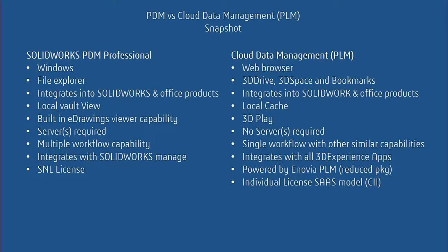You can also set up a file structure utilizing bookmarks, which is like Windows. Both products integrate into SOLIDWORKS and Office products. PDM creates a local vault view for the client installations to access files from the local C drive, and Cloud Data Management also stores files locally but are stored in a local cache folder. Both programs offer viewing capabilities.